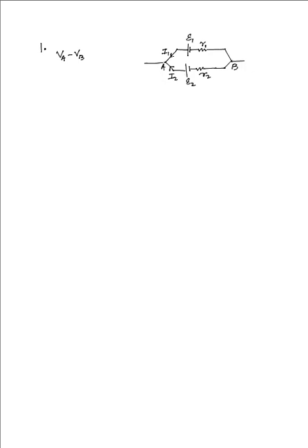Now, VA minus VB is simply equal to, considering the upper wire, the EMF E1 minus the current that is flowing through it multiplied with the resistance. Considering the sign convention, that will be negative because that is against our sense as we move from A to B, considering potential drop to be positive and potential gain to be negative. And so we have this to be I1 R1.